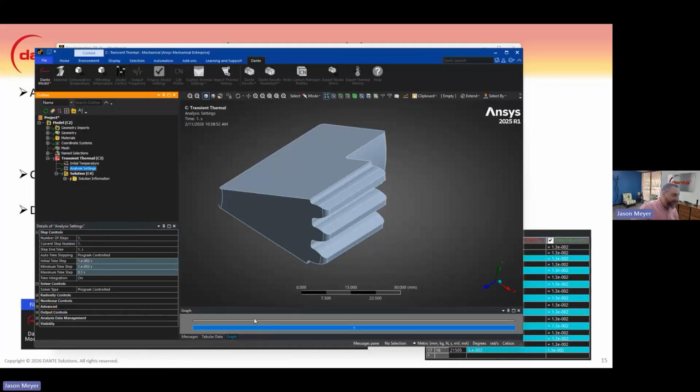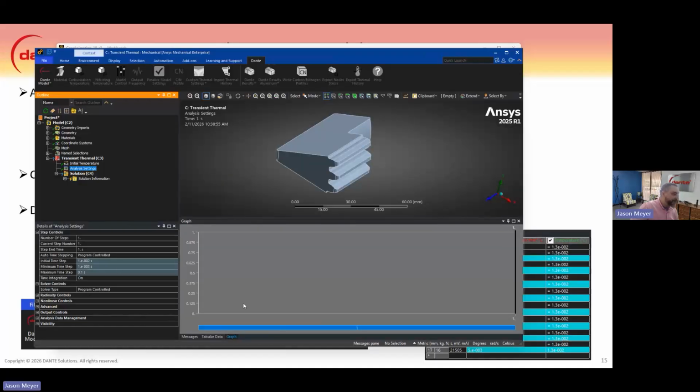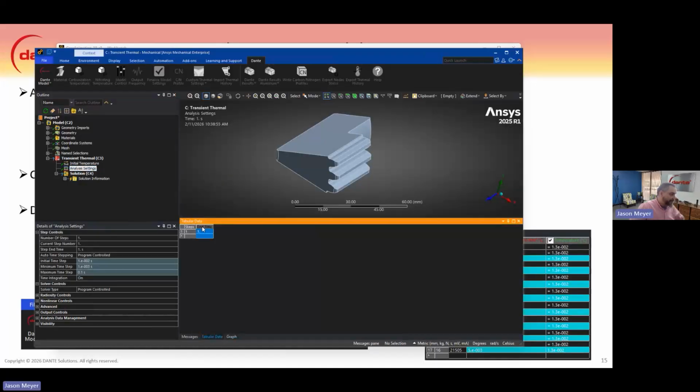And then for the analysis settings, this is where we define our steps and our step numbers and everything. We have our step times. We can just paste these in here directly from the Excel that we had. And that'll bring us up to 23,120. Okay, so that is our full process time. I'm going to copy that because I will need that later. So this set up our 16-step boost and diffuse process here just by pasting them directly in from that Excel document that we set up.